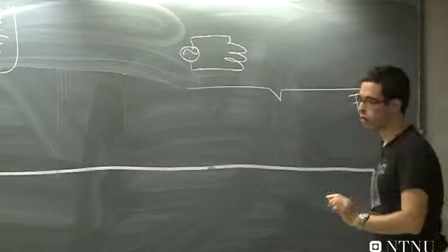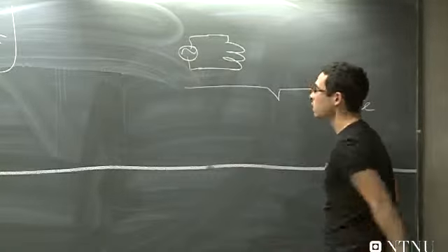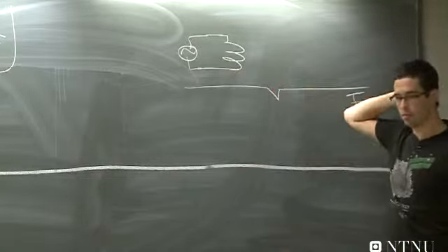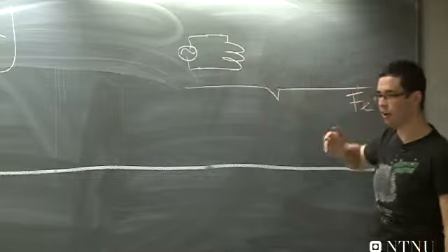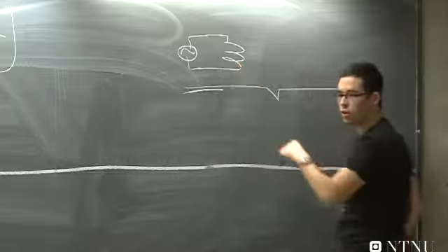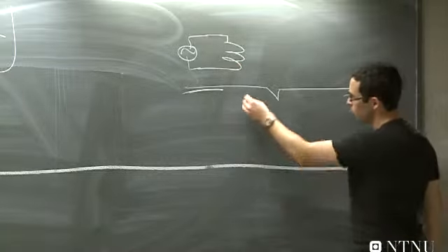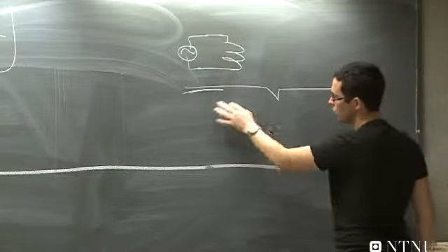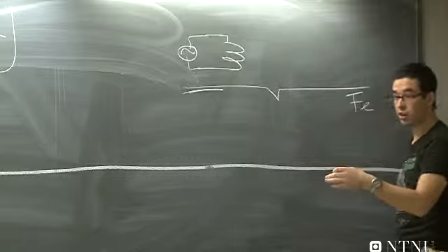And I make an alternating current source. So you have some magnetic field generated from this, but it's varying in time. So I'm going to induce eddy currents on the surface when I hold the coil down to the surface. But if I'm approaching such a crack, well, first of all, this causes some heating.